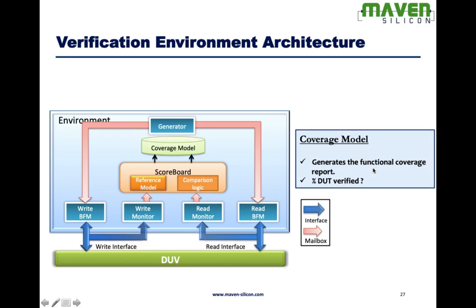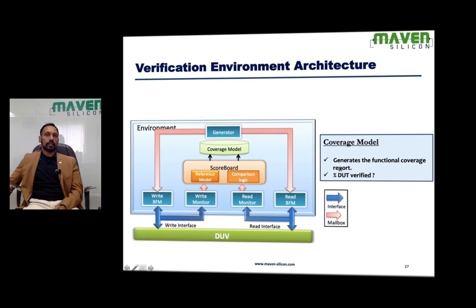There will be a coverage model also. Basically, this coverage model generates the functional coverage. We will explain the details of how we can implement the coverage model in SystemVerilog later during the language course. But what you need to understand is we generate functional coverage for every test case. If the comparison is successful, then the functional coverage will be generated. And with the help of functional coverage, we would be able to identify how much we verified in terms of functionality.